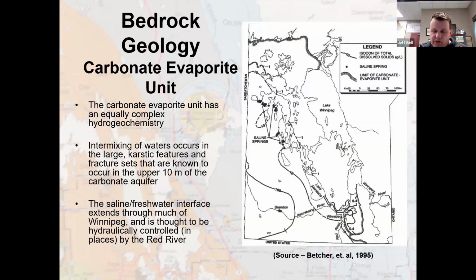A lot of the recharge dynamics are also changed by the way that the formation is fractured. There's no flow in limestone bedrock without any fractures or breaks. All the cracks, voids, joint sets, and karst features, that forms the basis of the aquifer. Without those fractures, joints, and voids, we really don't get any flow from it. And that's why the aquifer is so strong, yet it's also why we sometimes see dry holes in it.